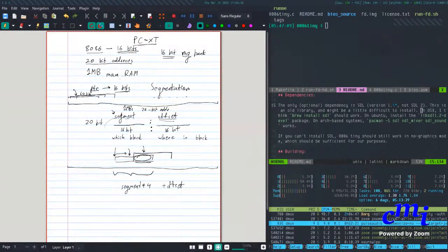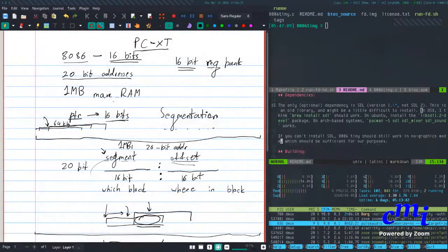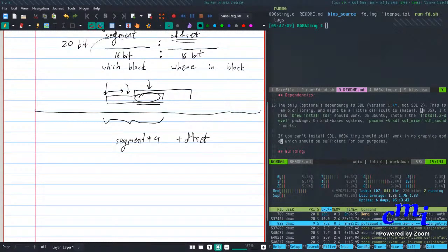No, it doesn't. Which means that you will have to manage where you store the program, from this location to this location. There is a very specific location where the processor starts executing from when it boots up, but that is fine. But you will have to manage the data. You will have to have a data layout pre-planned when you want to execute the thing.